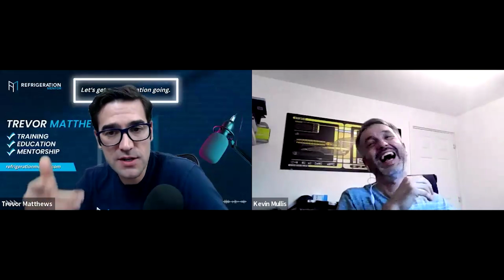I was having a conversation yesterday or the day before. Was it yesterday? Yeah, my friend Paul from Hill Phoenix, and he does all field startups. It's similar to some of the stuff that you do out there. He was telling me, I'm getting calls that Bitzer compressors are failing, and it's like, oh, it's a Hill Phoenix, or oh, it's the problem with the Bitzer. And then when they get back, there's 7 gallons in a 4-gallon oil system. I'm like, why is there 7 gallons in the system? Well, the compressor broke, they add some oil into the system and then don't take it out. Well, why are you adding it in the first place? There's a process to get it back, using compressor 2 and compressor 3 to get it all back. You know what I mean?